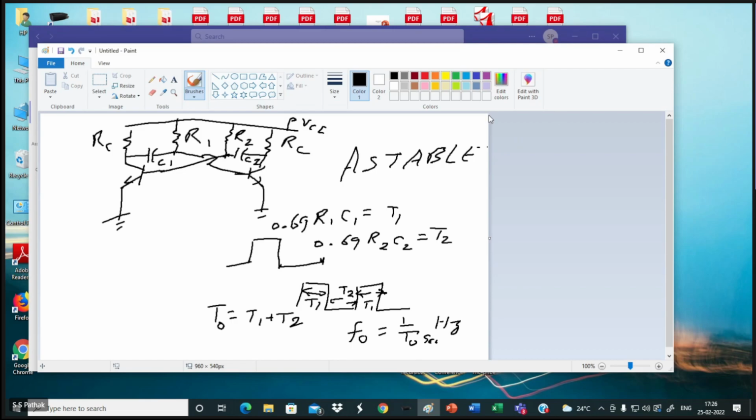Any question? Monostable multivibrator and astable multivibrator I have covered today. But remember, I have done only the collector coupled case, not the Schmitt trigger emitter coupled case, which I have done for the bistable case. These two are possible for emitter coupled cases also, and that will once again be easy to design using the 555 timer or even the Schmitt trigger that you have made as a circuit in your lab yourself.